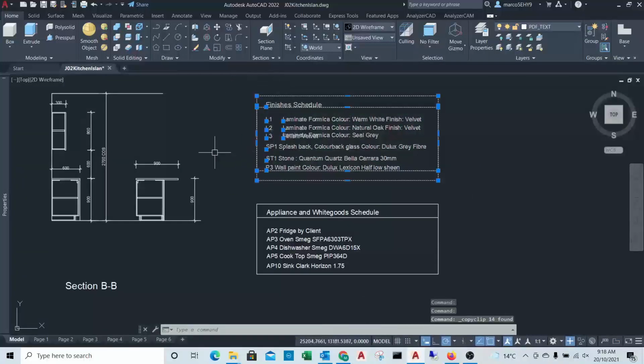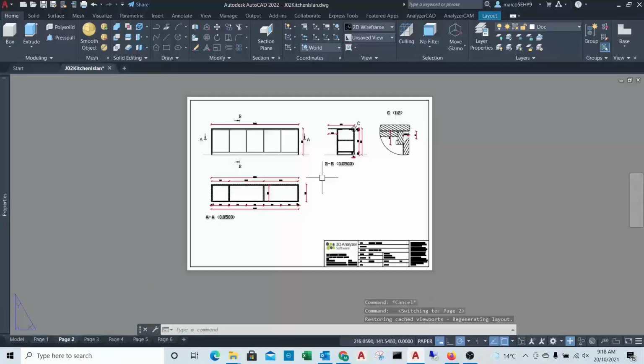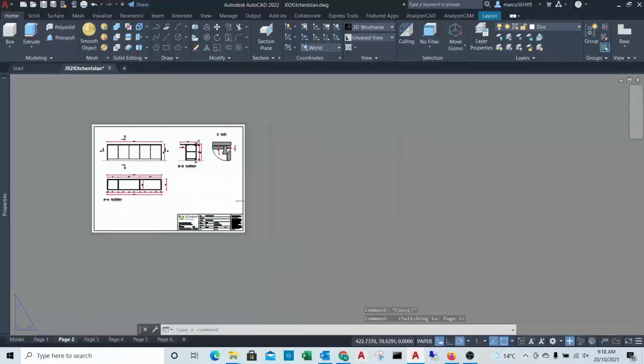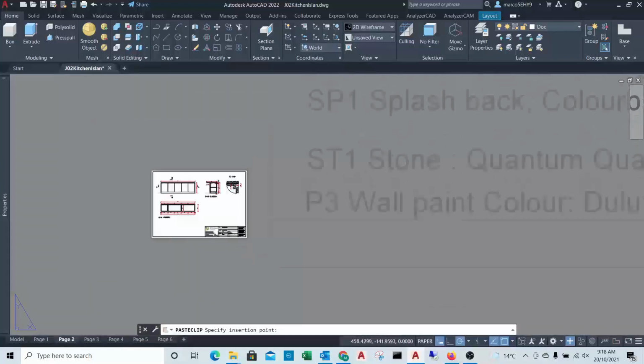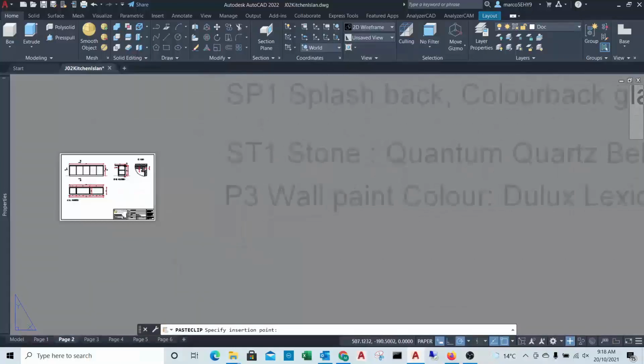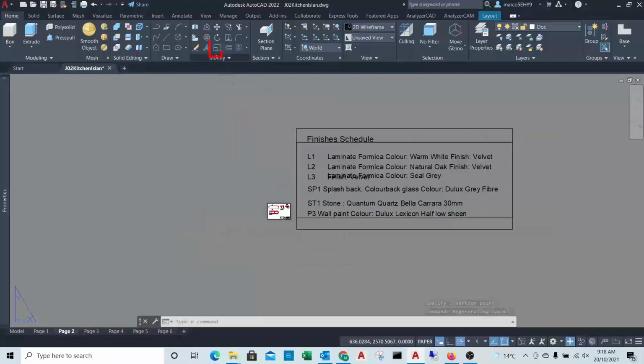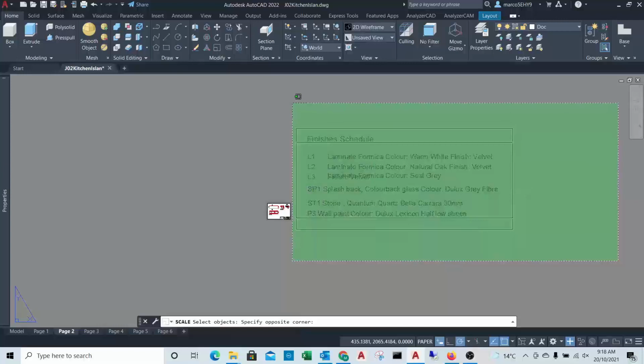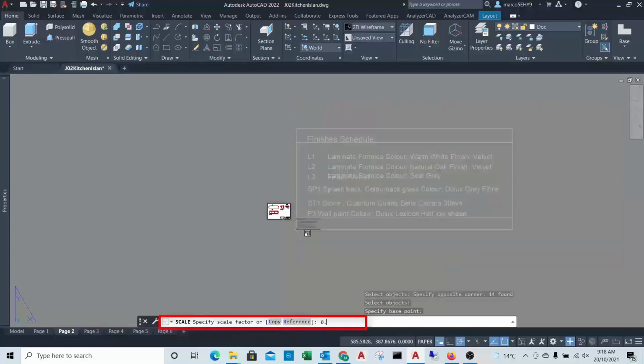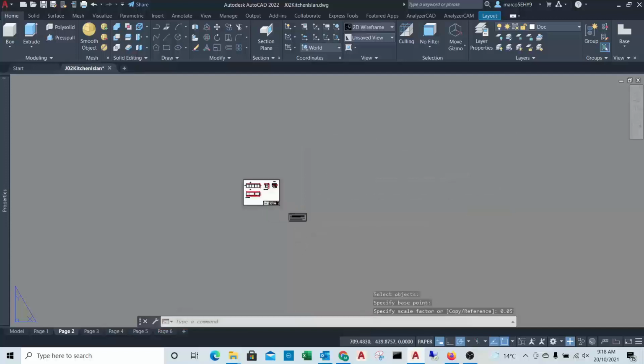I do this by highlighting the area and pressing Ctrl+C, this places it on the clipboard. Then I will paste it into our layout with Ctrl+V. It comes into our layout at the wrong scale. Our layout is 1/20 scale, and the model space is 1:1 scale. We can rescale the description like this, typing in 0.05 as that is around the 1/20 scale.